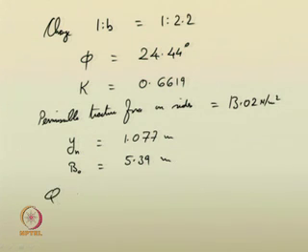Q was found to be equal to 11.067 meter cube per second. So, this is greater than the required one. So, you can adhere with this design parameters and you can proceed with the channel dimensions. You have to add additional freeboard quantities, and subsequently the channel is designed.